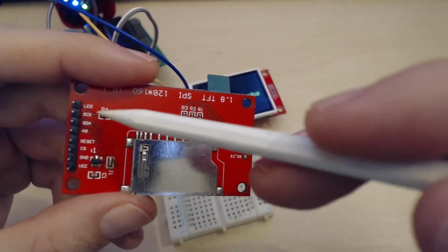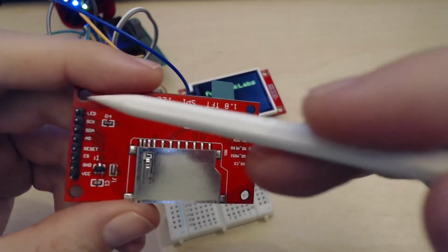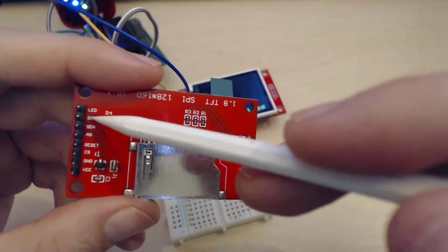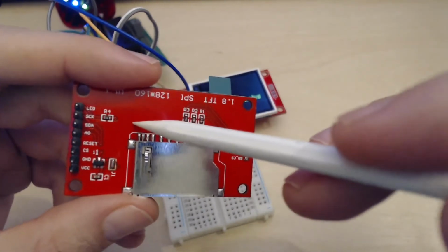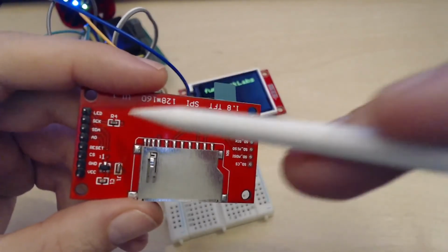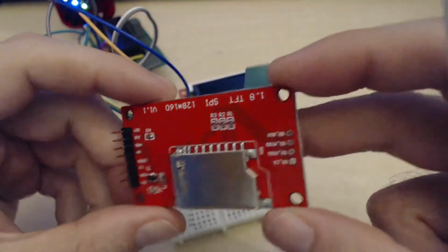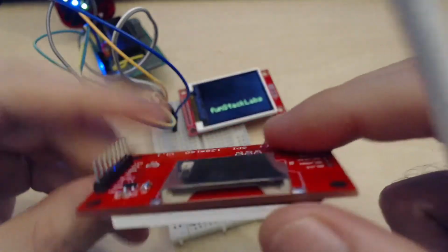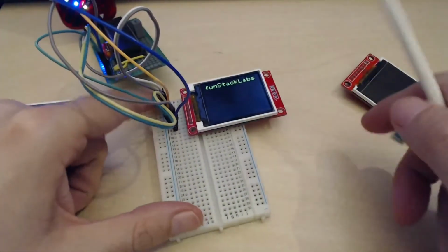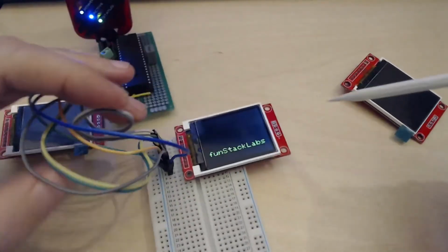Same with your LED, right? If you are using 5 volts to drive the LED, you need to pop in a current limiting resistor there too. But if you are using 3.3 volts, there is already an internal resistor on the module, so you can just directly drive it from 3.3 volts. That's not a problem. So yeah, that's pretty much all we have on the back of it and all the pins. And let's have a look at our prototype a little bit, and then we can jump onto the schematic and the code, etc.